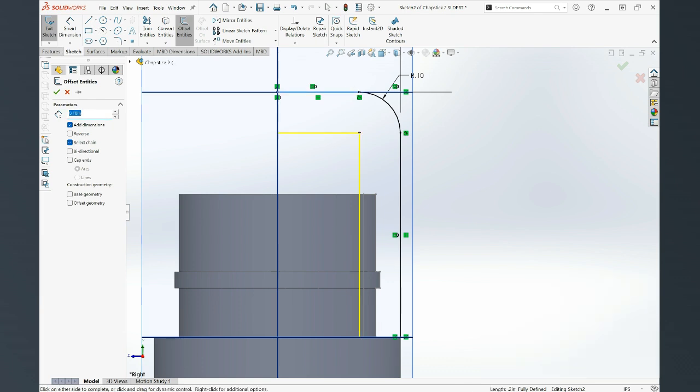I'm going to click here. And as soon as I did that, we see this yellow preview of what's going to happen. The offset parameter is 0.1. That's too big for what we want. That's thicker than our cap is. Our cap is more like 0.04 inches thick. So now when I did that, you see the offset moved closer and it kind of looks more like the profile of our cap. What could happen is we could offset on the other side by clicking reverse. That's not what we're doing in this case, but later down the road you might need that.